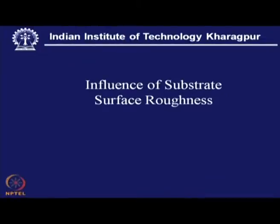If it is a particulate deposition coating like plasma spraying, then the substrate also needs to be roughened, and the scale of roughening of the substrate which is going to receive this sprayed layer and the substrate surface which is going to be a receptor of PVD coating, their requirement may not be the same. So, influence of surface roughness affects the coating.